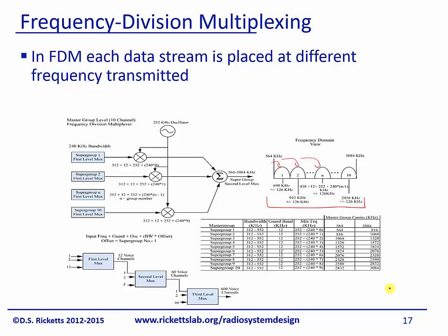communication. Just one little side note on fiber optic. The one thing that is just starting to happen, but it's not really mainstream, is that in the past, fiber optic has been a binary on-off key. So you get a 1, a 0, 1, a 0, 1, a 0. And the reason they did that is they can basically transmit, like I said, 40 gigabits or 100 gigabits over optical fiber because the transmission loss is so low. It's very difficult to build electronics that can do 40 and 100 gigabits, but the basic idea of the fiber is it's open to almost unlimited bandwidth, or I'll say relatively unlimited bandwidth. So there hasn't been the necessity to do complicated things like amplitude and phase modulation.